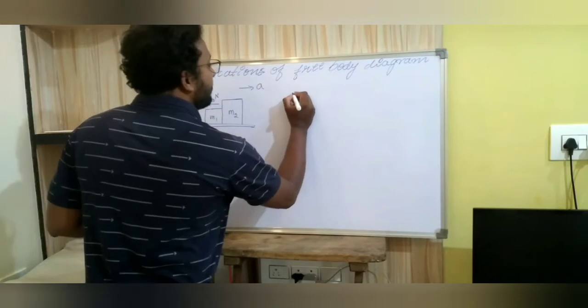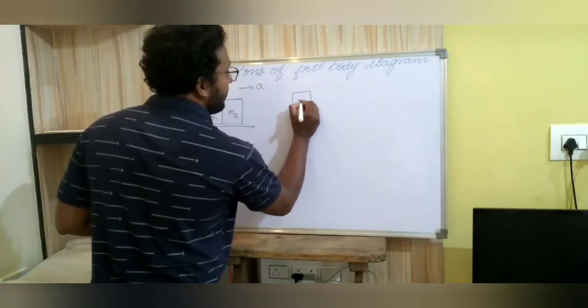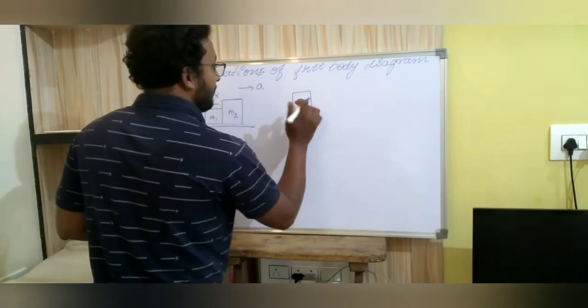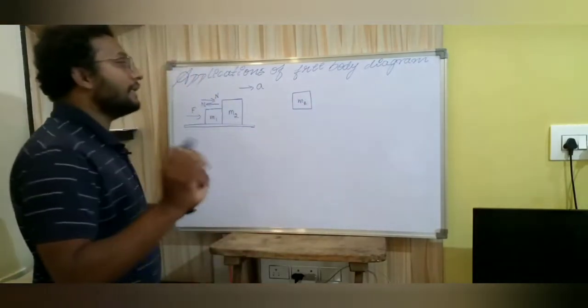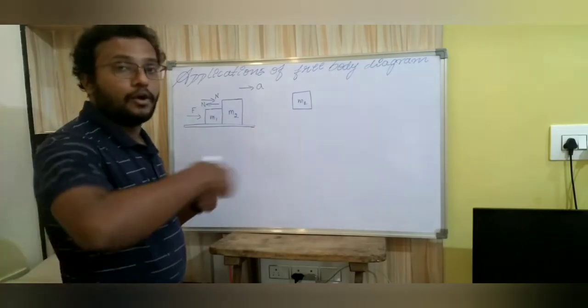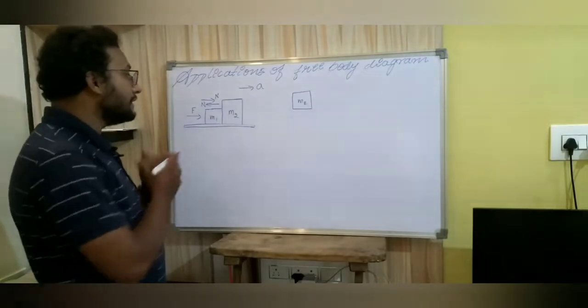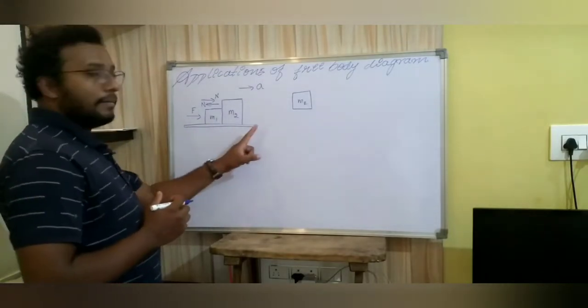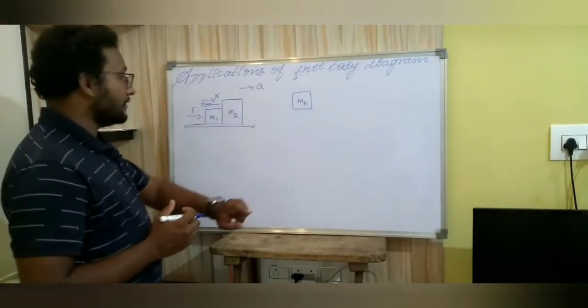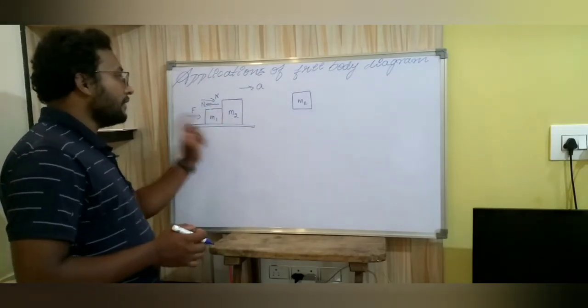So let me write the free body diagram for the block m1, neglecting everything in the surroundings of m1, so m1 alone is considered. On this block, along the x-axis, there are 2 forces acting that we can see in this diagram. One is the applied force along the positive x-axis, and the other is this normal reaction N applied by m2 on m1.